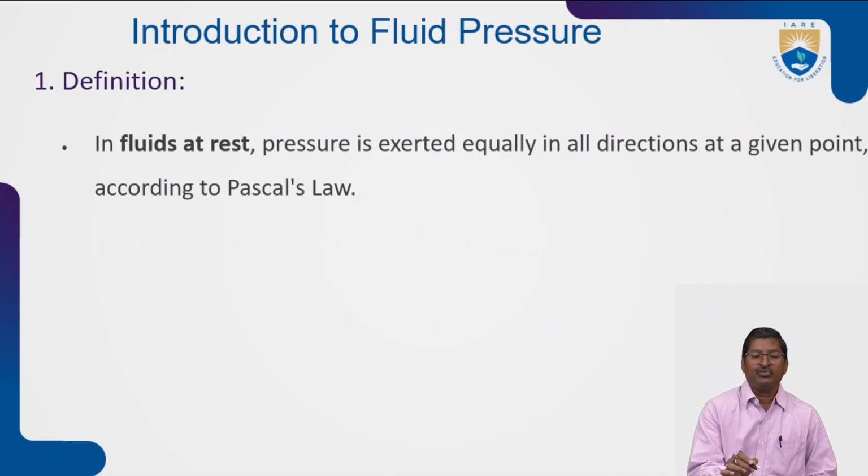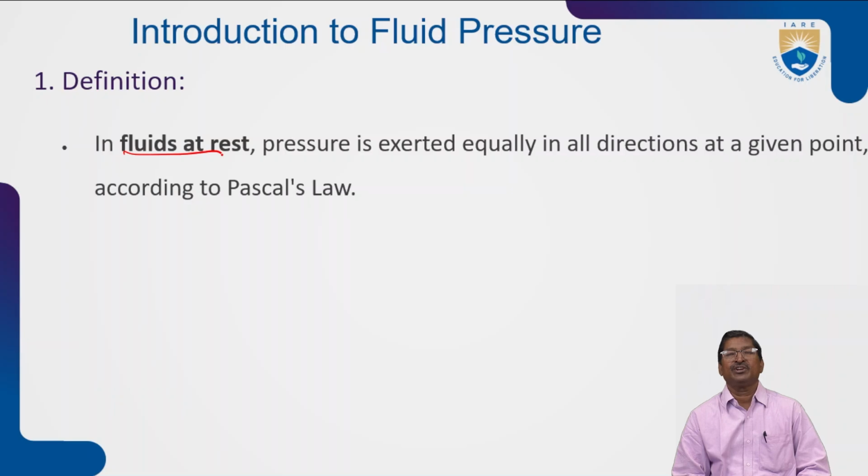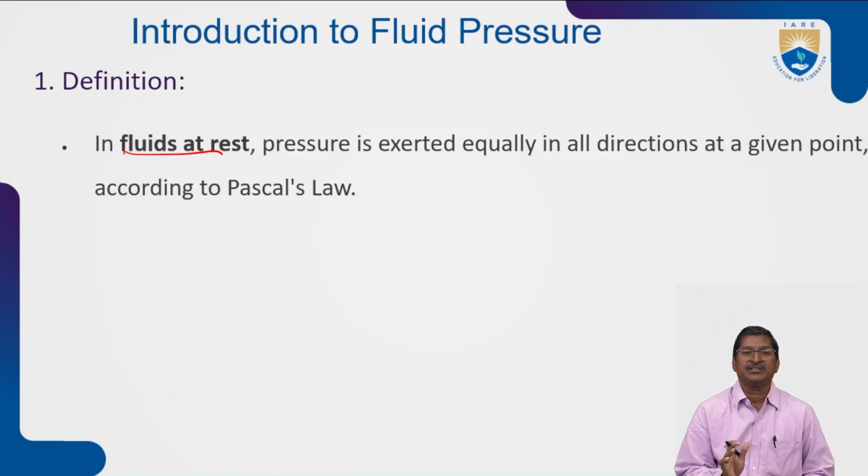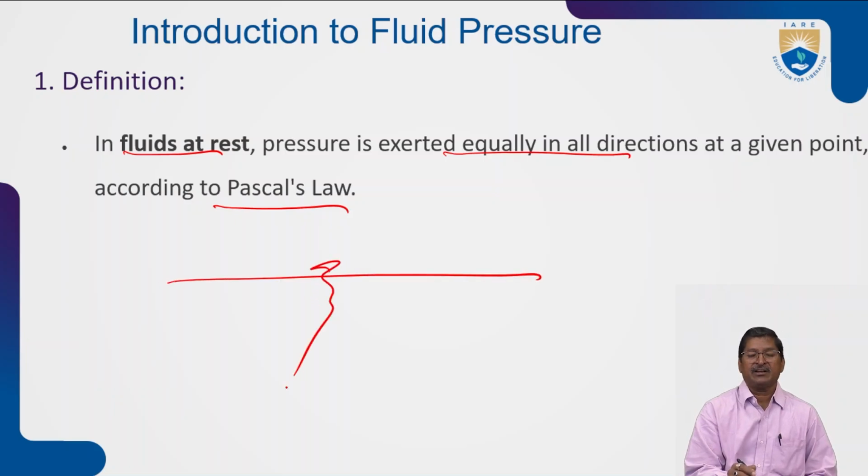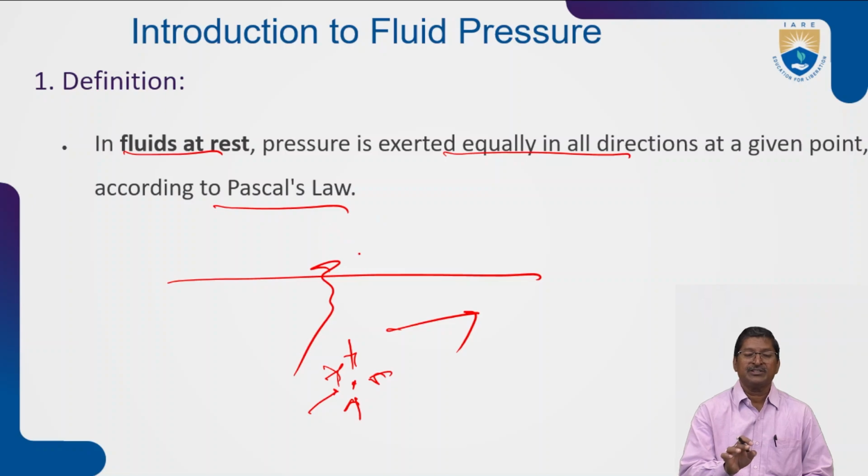See here, fluid at rest. What is the meaning of fluid at rest? If the fluid is not moving, it is stagnant, then it is called fluid at rest. Pressure is exerted equally in all directions, which is called Pascal's law. That means if you take a point in this water and the water is not moving, then the pressure will be the same in all directions, which is called Pascal's law. The condition is that the fluid is static, that is, the fluid is not moving, the fluid is at rest.